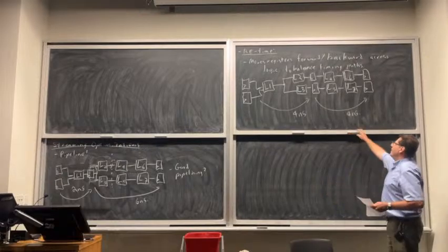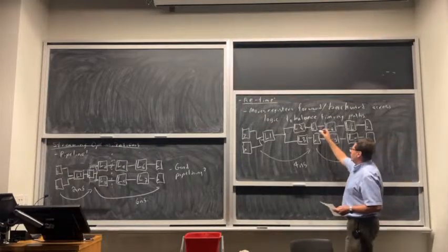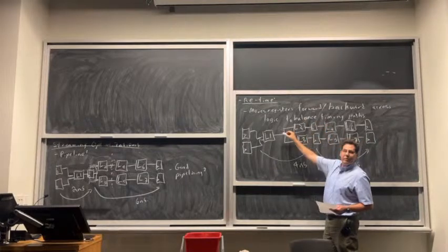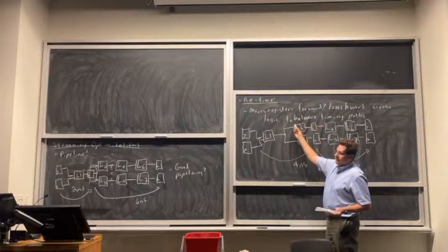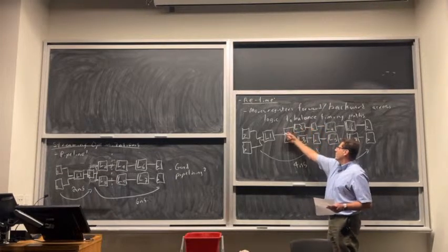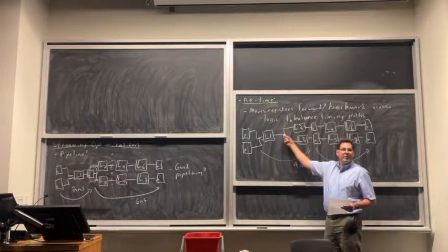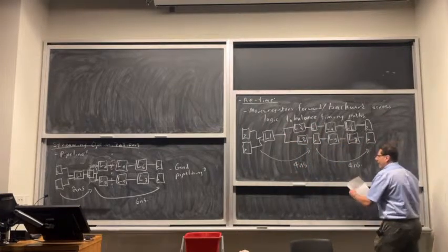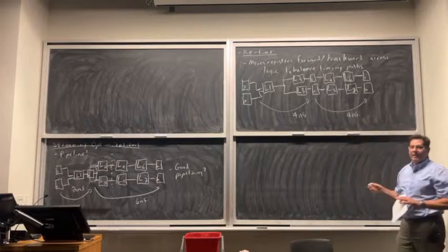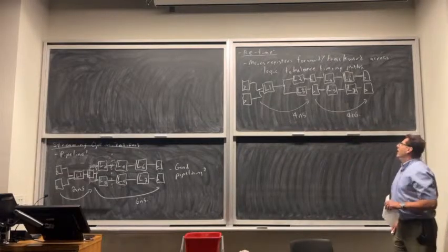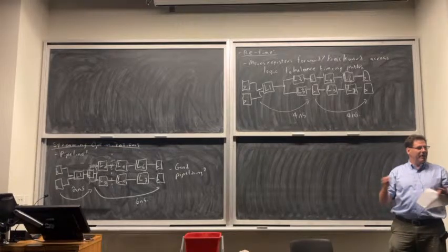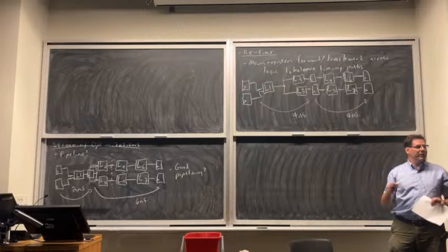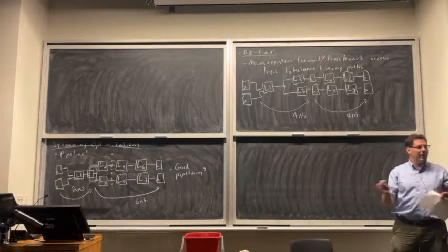Okay, and in general, retiming, I just showed you forward retiming, but in general, it can also move things backwards. So for example, if I started out here, and I wanted, it's not actually useful, but let's say I wanted to retime these back, these two copies would actually merge into one register. And a retiming algorithm will evaluate both. Because in a more complicated circuit, you may find both of those things are beneficial. So every register, some might get moved forward and duplicated, some might get moved backward and merged, and some it's going to find I can't move it, right?